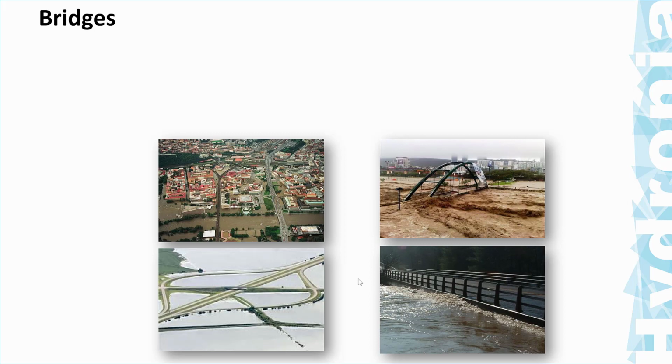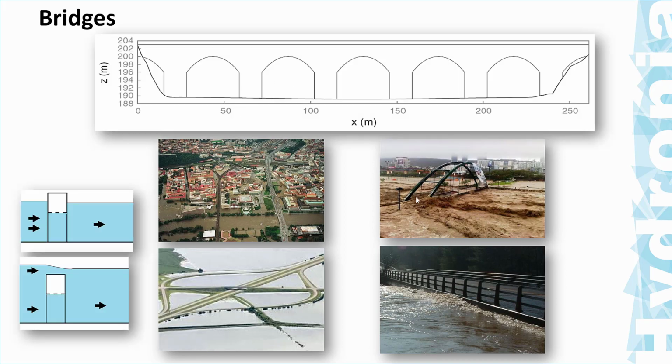The model can handle breaches of many different forms. Virtually any form of breach can be considered, such as arcs. The breach can overtop. You can calculate the flow by the pressure flow and the overtopping, and that is very important because that helps improve the design of breaches, or at least understand what can happen if the breach is overtopped in a flood, and how that can exacerbate the flood upstream due to the backwater effect that it can create.